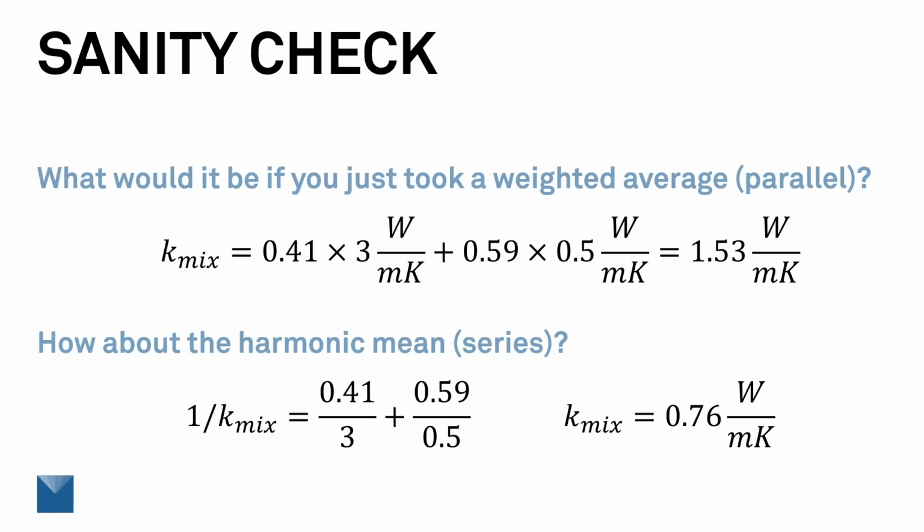We can do that calculation by setting the thermal conductivity of the soil material to 0.2. And if we do that, we come out with a conductivity of the mixture of 0.74. So we can see that having the rock in the mixture maintains a much higher thermal conductivity than we would get just with the soil itself.